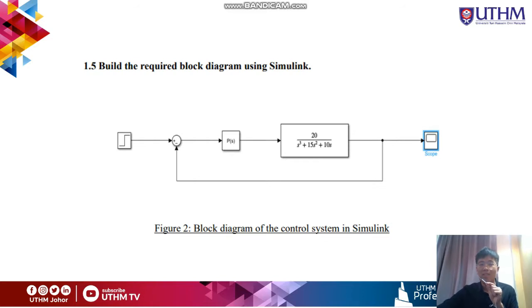And for the last part, 1.5, build the required block diagram using Simulink. This is the block diagram, which will have a transfer function of 20 over s cubed plus 15s squared plus 10s. And that's all for my part.